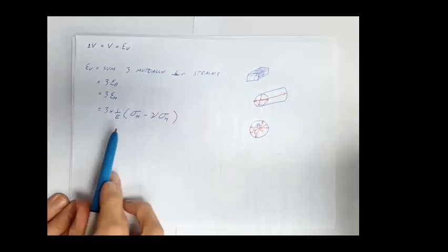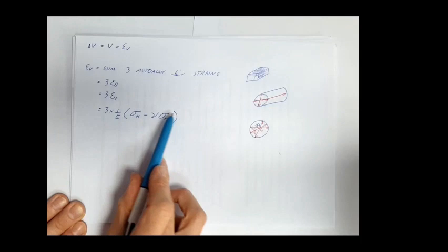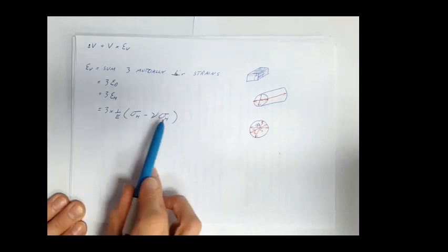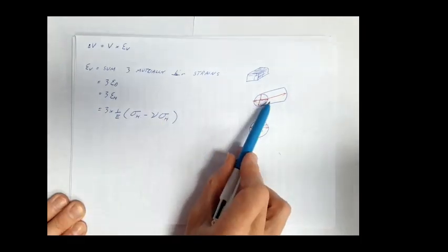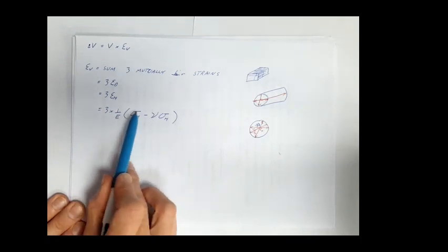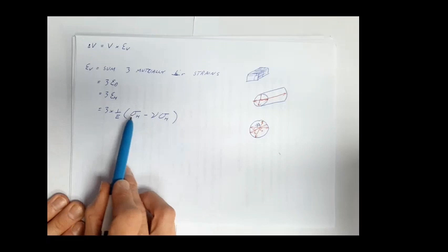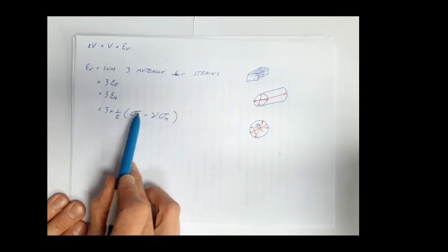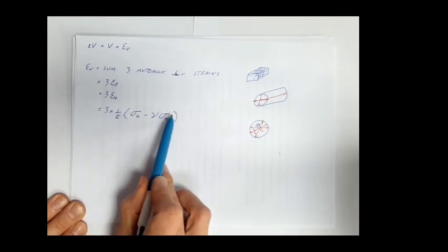Okay, remember we showed this last time that actually the strain was the sum of 2 components for our cylinder. It was our stress over Young's modulus is strain, so the strain is made up of 2 components, the strain in the hoop caused by the hoop stress and the strain caused by the longitudinal stress.